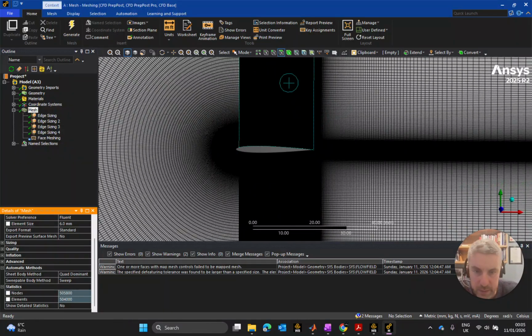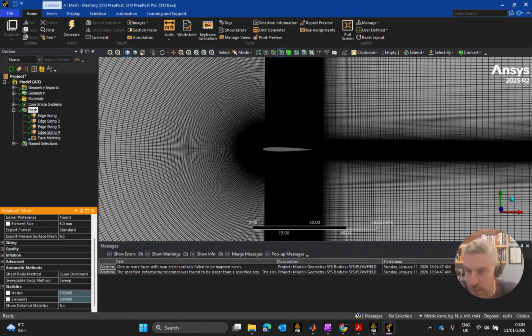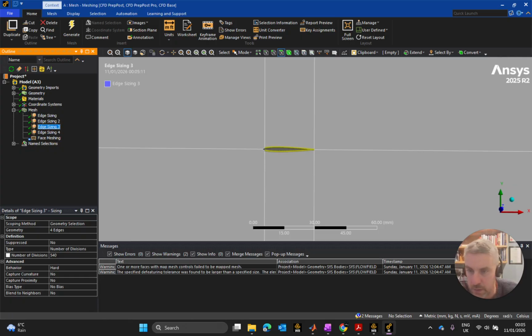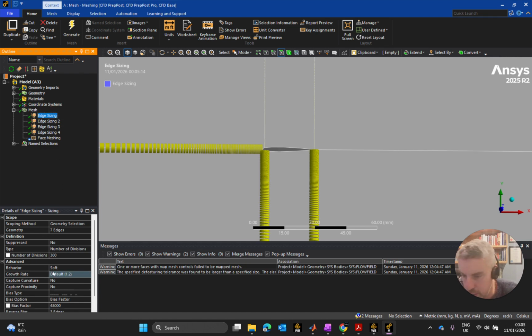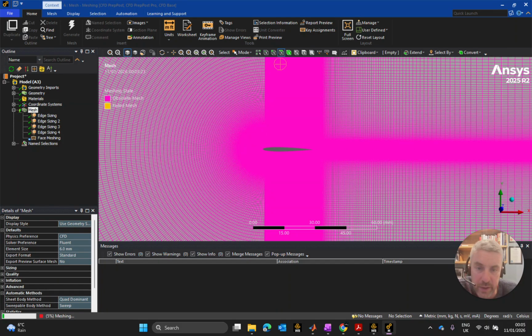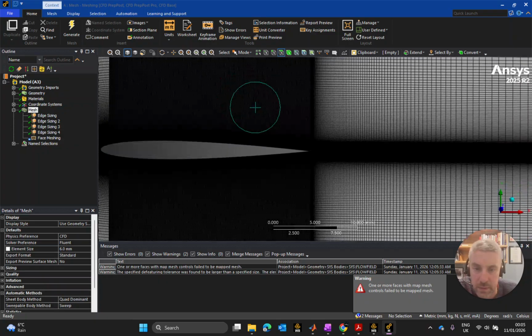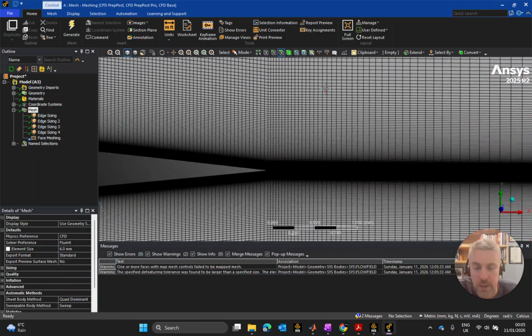And the other thing is I can reduce the bias on that somewhat, because there's no need to have that so well resolved up there. Alright, so let's try that one. Bias factor 48,000. Let's bring it back to 42,000. You know, if it has to be that well resolved up there, then the argument means that it should be that well resolved next to it. Slightly better there. You can really just see a nice even transition. It's getting there.